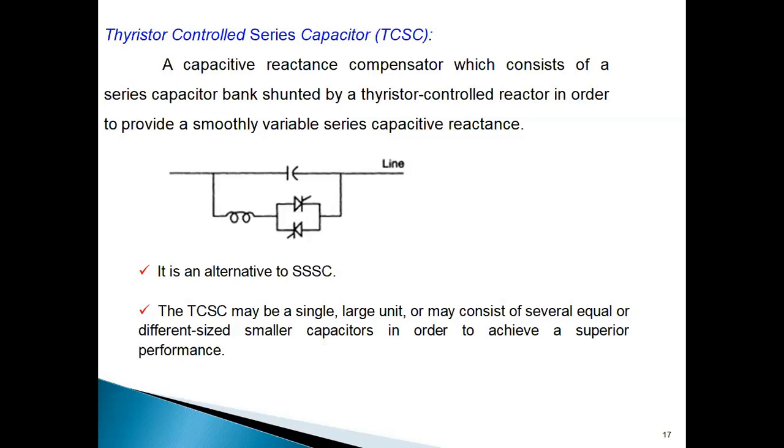So when I have control over XC, by increasing the value of XC, XL minus XC will be brought down. Because of this, the IZ voltage drop occurring in the transmission line due to the presence of reactance will be reduced, and finally V2, the receiving end voltage, will be enhanced. Let me repeat once again. Remember this formula: Z equals R plus j(XL minus XC).